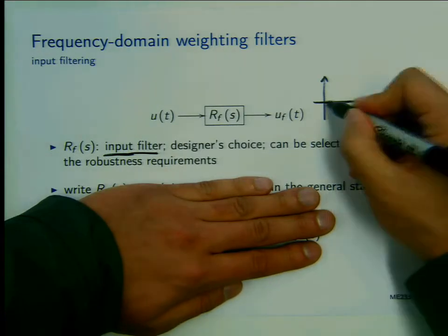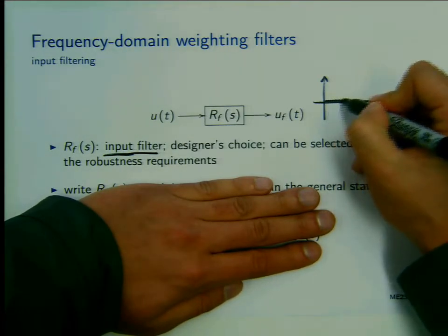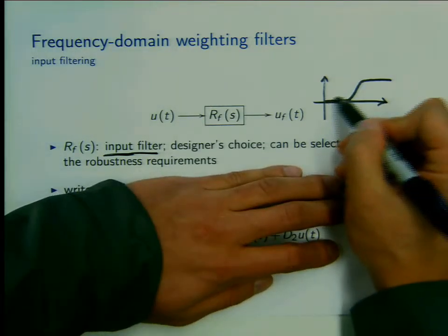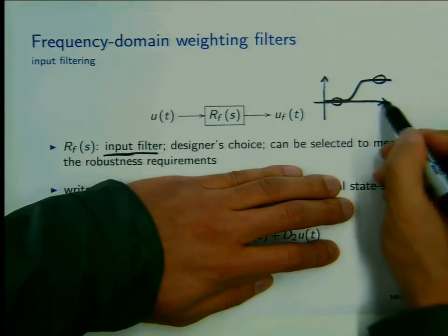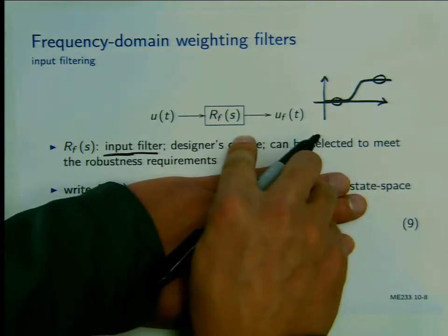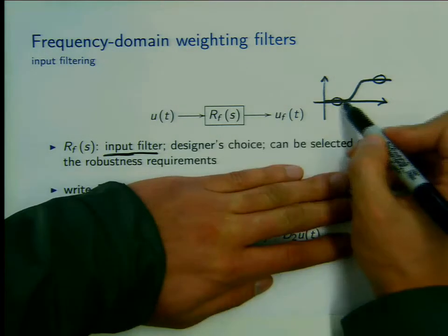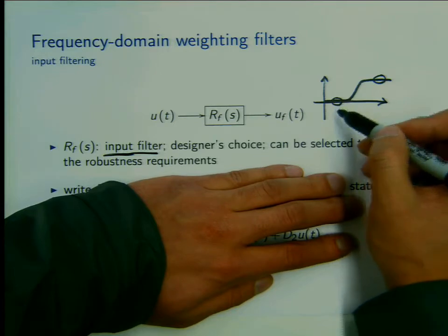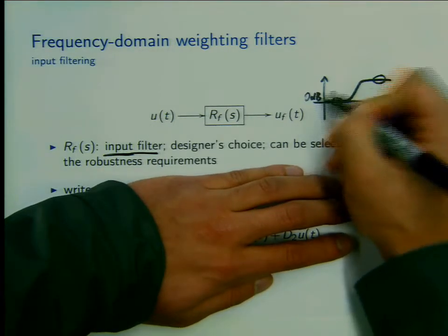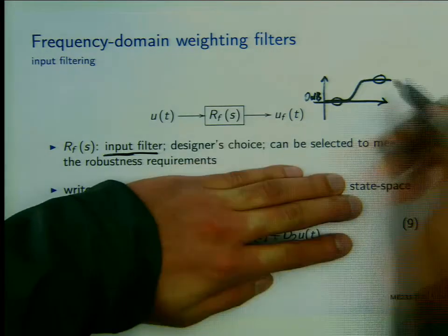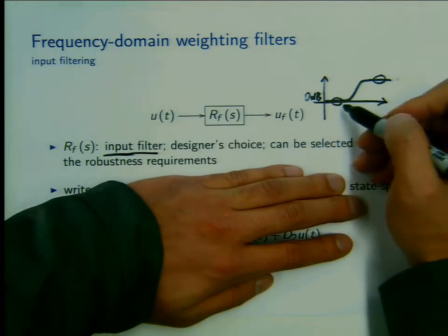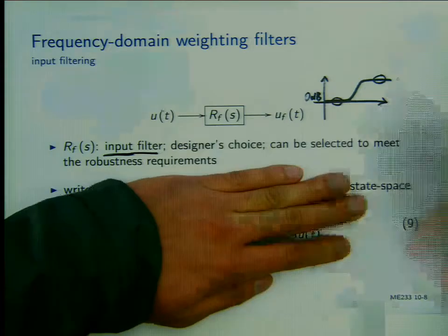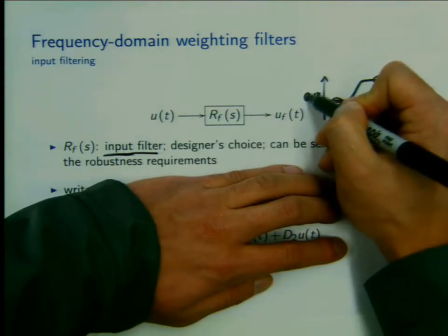Let's go into some more details even. For whatever kind of high pass filter, let's say it looks like this. You have to select the low frequency gain and the high frequency gain. In this case, what's one convenient design to select the low frequency gain of RF? 0 dB. That should be a little bit easier to design. I should explain this a little bit more carefully.